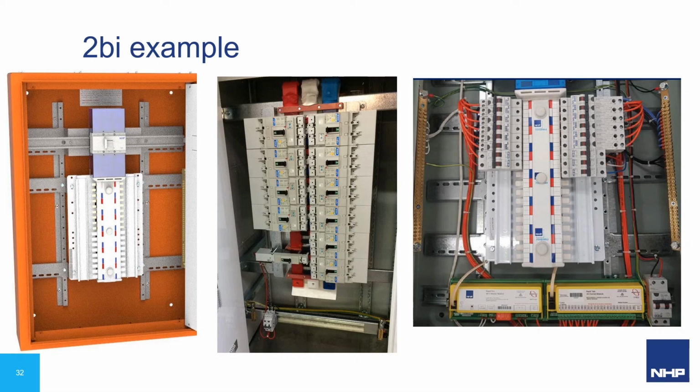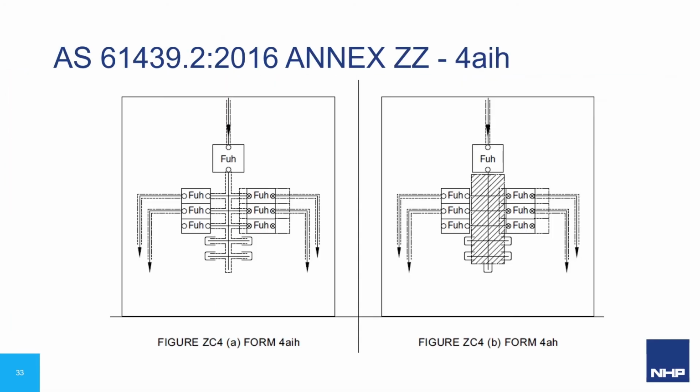There is no strict IP2X requirement for the load side of the functional units or terminals for outgoing conductors, but it is typically achieved in practice. Tee-off caps are required on the busbar if no MCBs are fitted.